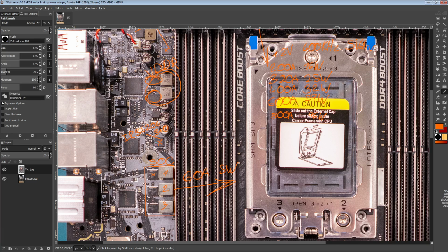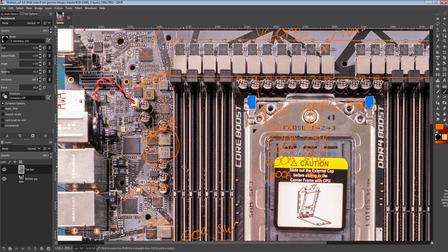For comparison, let's just take Gigabyte. Gigabyte's top-end motherboard uses like 3 discrete MOSFETs for its entire memory power delivery. Gigabyte's power delivery for memory is like 1/5 the current capacity of what this has. It's still plenty good enough for memory overclocking, especially because I'll have to see about this, but I'll be surprised if Threadripper doesn't do the same thing as Ryzen does, where memory speeds above 3800 megahertz are complete wastes of time, just because your FCLK is not able to go that high.